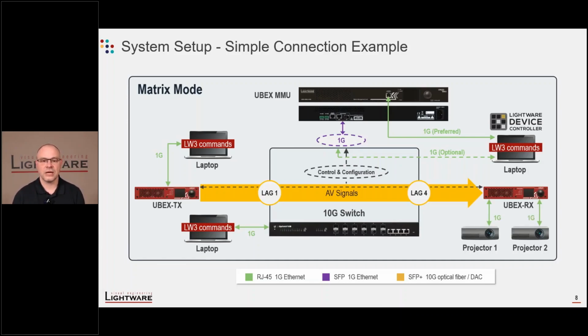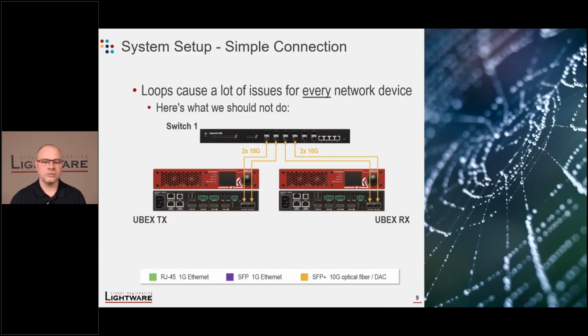Because if you have, let's say, LAN control-enabled devices like projectors, then somehow you need to send them information. And this is actually possible if you have that. Now, as you see in this connection, the devices' gigabit Ethernet ports are not connected to network infrastructure equipment like network switches. And there's actually a reason. And that reason is a spider web of issues, something called a network loop.